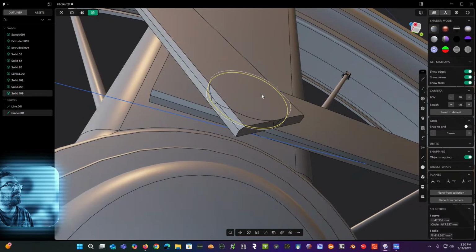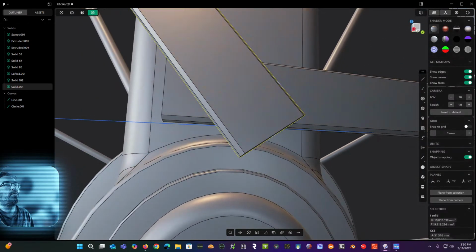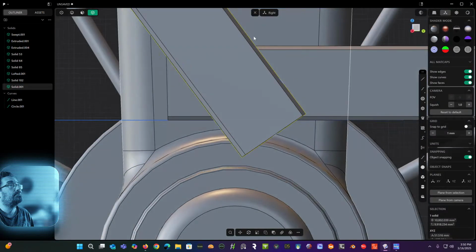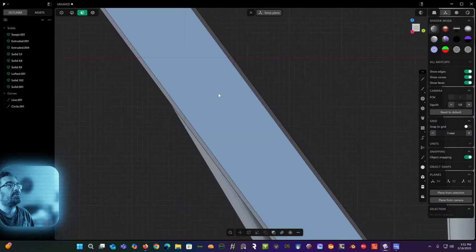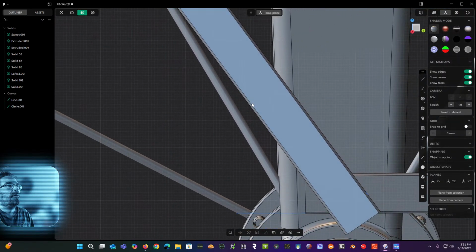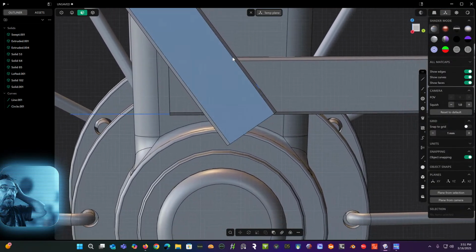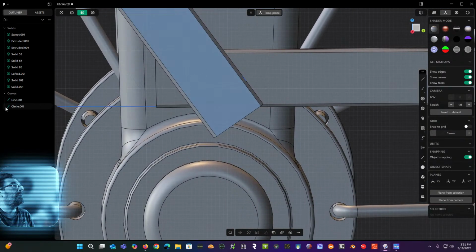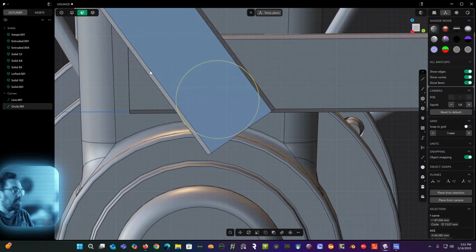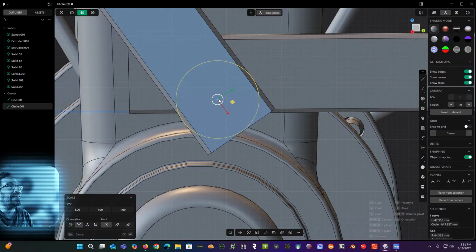I mean, it worked, but it didn't cut all the way through. All right, so we will have to make it slightly bigger because of the angle, probably. But the way I can go about that, too, probably, is to make a temporary construction plane of that piece here to where it's perfectly on that piece. You could probably see that it's off. Let's just make it a little larger. So I'm just going to scale it up like a hair, even maybe a little more than a hair.